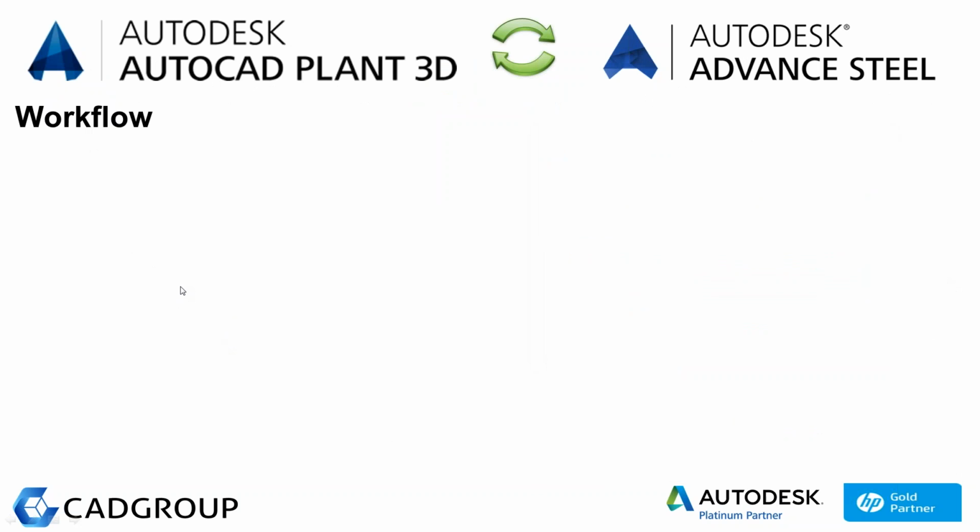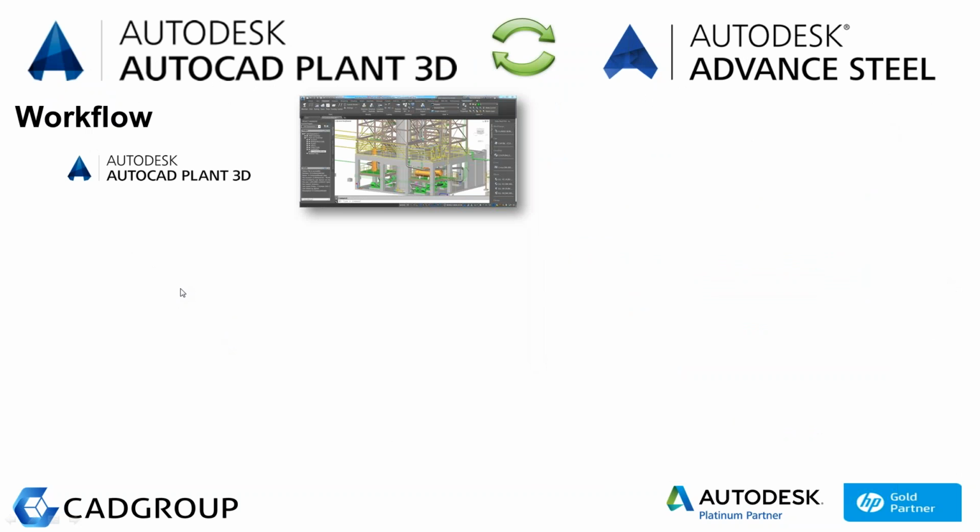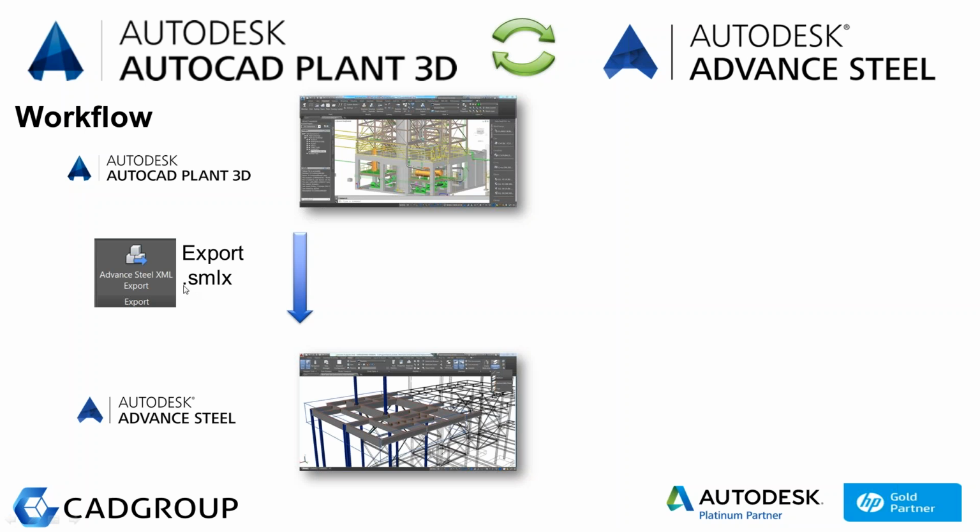All right. So the workflow. From Plant, what we can do is export out the SMLX file. Okay, the same format that we were using from Revit. And from Plant, we can import the SMLX file into Advanced Steel. Okay, so the next step is we can go and add all our connections and do everything we need to do inside the Advanced Steel model. Okay, and this can be XREFed back into the Plant project. All right, we'll go through this process and have a closer look.